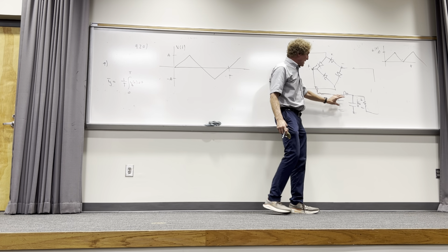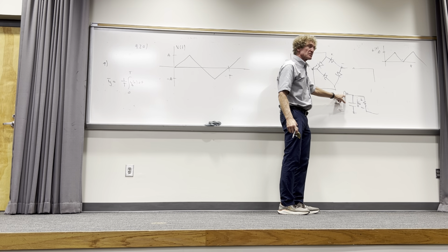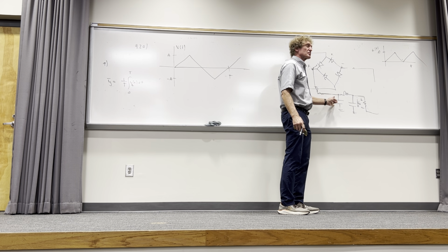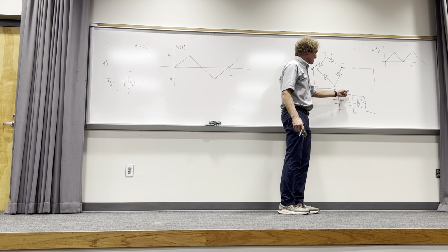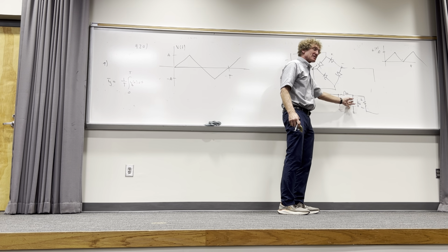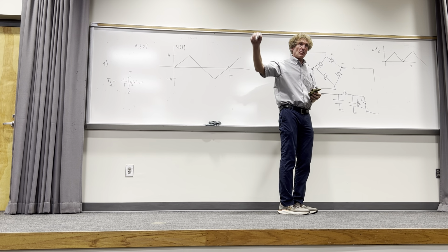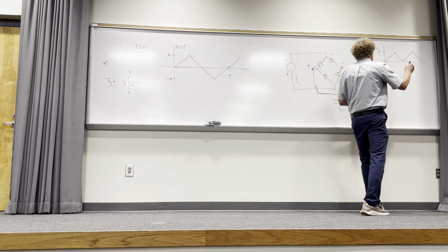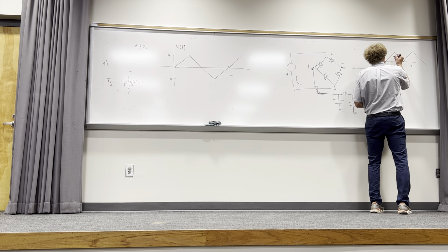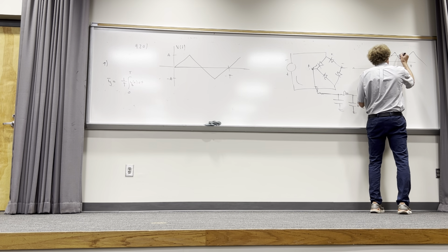What these do, when they charge up, that inductor, first of all, is going to slow down any kind of fast transitions. Y'all with me? That capacitor is going to charge up and it wants to maintain the voltage on there, depending on what the load R is, but this inductor slows it down, and then this capacitor gets rid of any additional ripple voltage. So the output waveform, once you do rectification, is basically going to be just the DC value of that thing.